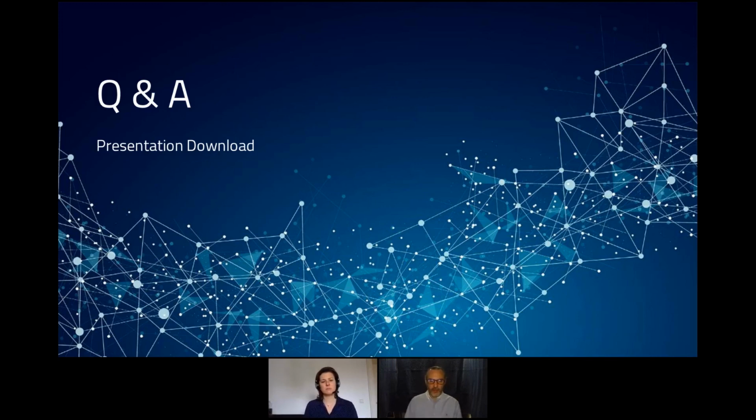Yeah, exactly. So something that's sort of forgotten about, like back in the old days of writing code and debugging on embedded systems, a typical technique would be printf type debugging, where you use small instrumentations in strategic places throughout your code, and then obviously when the code executes that location, you can get a nice little message on a terminal or something. So we still support that type of functionality in our tool. There's a small bit of code you can link in and then instrument parts of your code that you want to see happen.